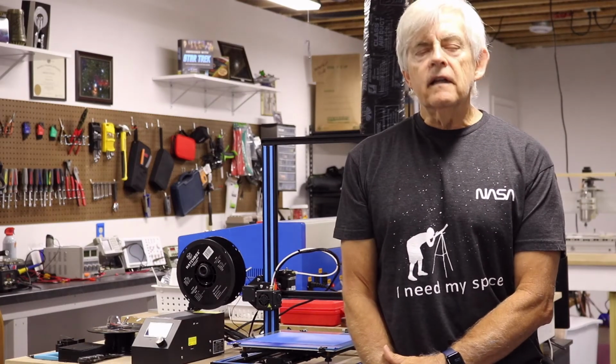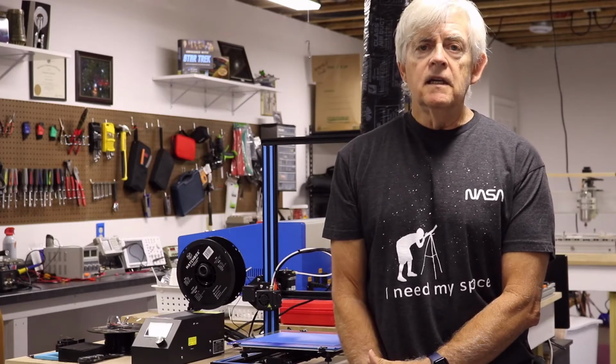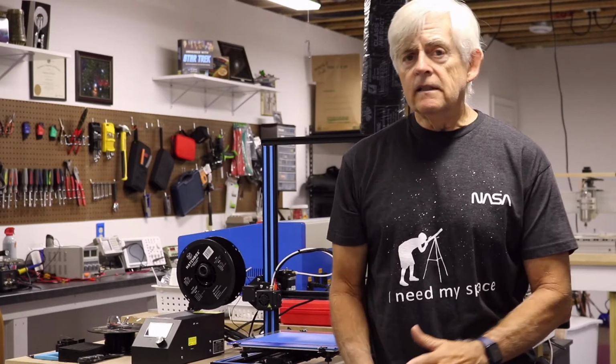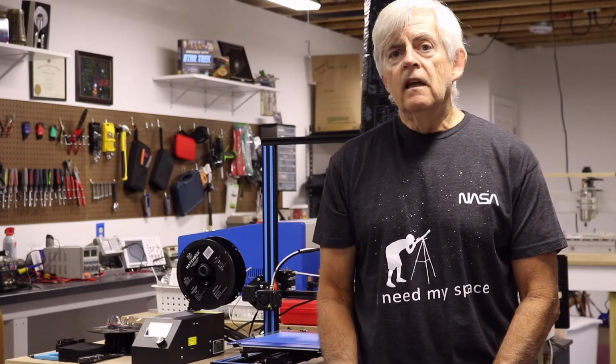Hey everyone, in our last video we made a utility box, a project box, using the FreeCAD software, and today I want to show you how you're going to take that and create an STL mesh file and just how easy it actually is to do that using the FreeCAD software. And then we're going to export that and bring it into Cura 3D printing software, and I'll show you a little bit of the configuration of Cura for your 3D printer. So let's get started.